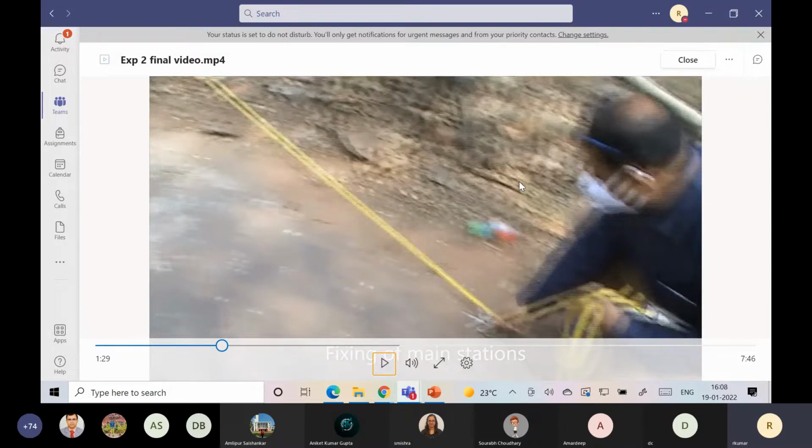So what you have seen, the ends are the two brass handles. The least count is 20 centimeters. As we have shown you, the tally is at 1 meter, 5 meter, 15 meter, and in between is 10 meter. So these are some tallies, and we can quickly find where the 10 meter is. This is the detail of the chain.